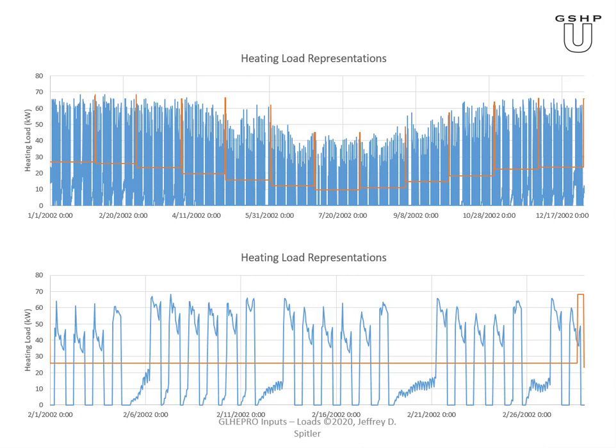It includes some hot water loads, which is why, in a cold climate, you see heating loads year-round. The blue here, these are the hourly loads for the year, and more or less these breaks are weekends when there's some kind of thermostat setback and not much hot water being used. And this orange line that runs through it, this is what we call our hybrid time step. So it's a monthly load here, January, February, March. And then at the end of the month, we have this peak that we superimpose on it.